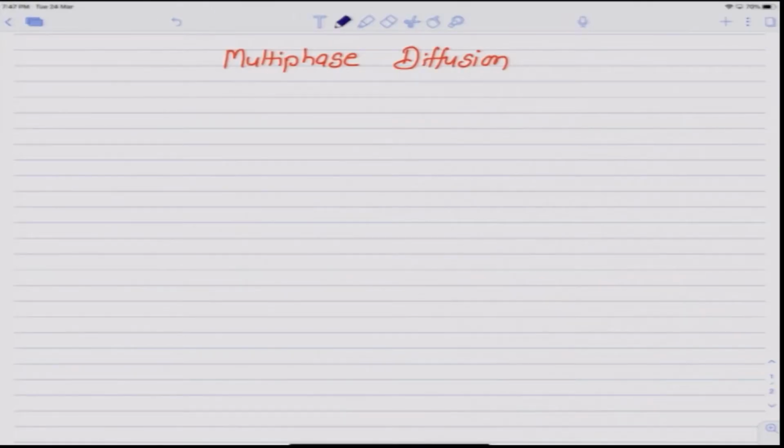In single phase diffusion, we had diffusion couples with terminal alloys having the same phases to start with, and even during the course of diffusion there was no second phase developed within the diffusion zone. So, the simplest system for the case of single phase diffusion is when there is a complete miscibility. So, if we consider an isomorphous type of phase diagram,